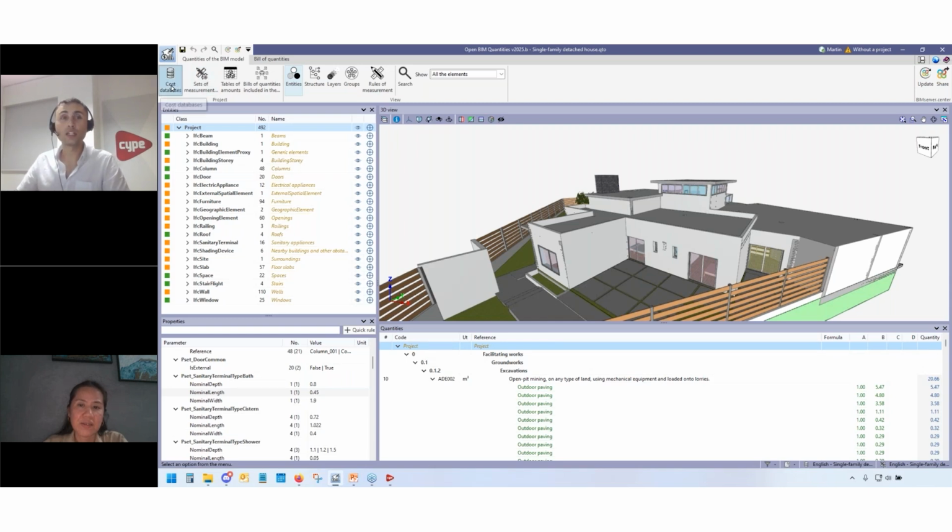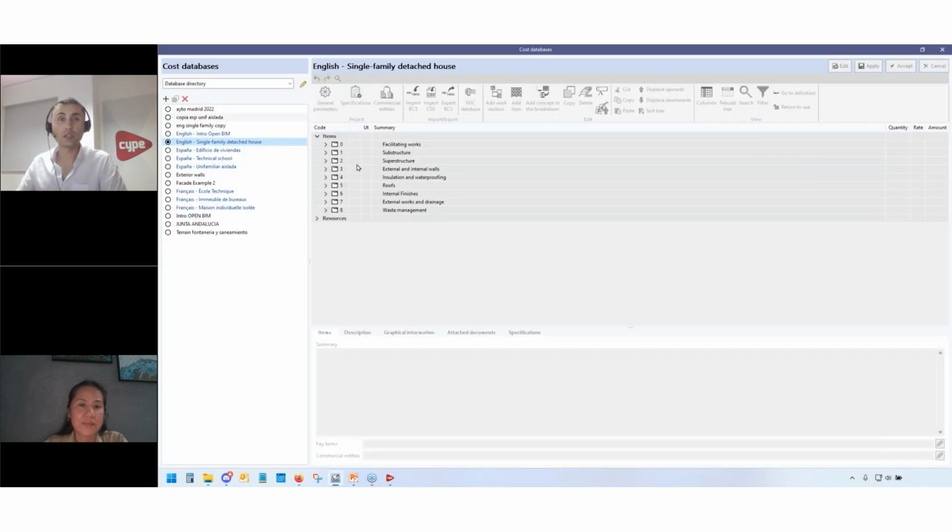Another challenge is the management of information from within the editing of the databases. We use the term cost databases to describe a list of possible solutions for different construction elements, with a description, a price, and a unit assigned to the specific solution. There are solutions that get measured in cubic meters, such as concrete, for example. There are solutions that may be measured in linear meters, maybe some specific sorts of walls, a pipe, or different ducts. And there are elements that get measured in units, such as a window, a door, or furniture.